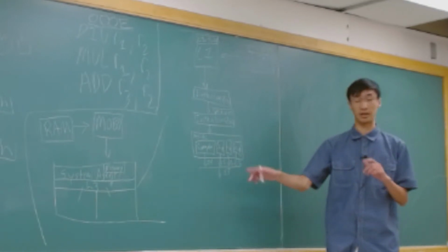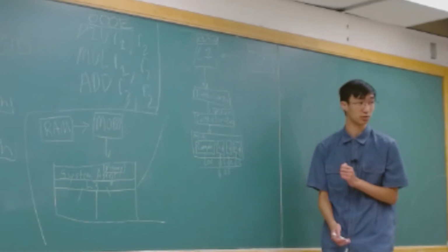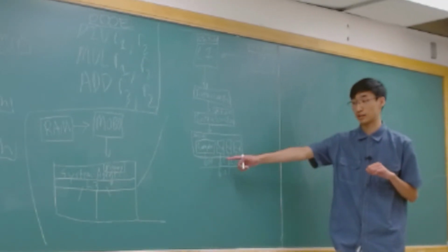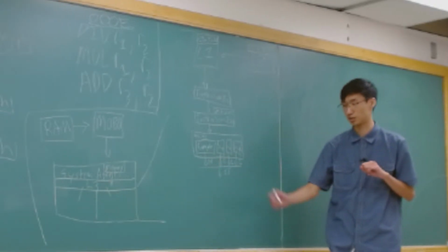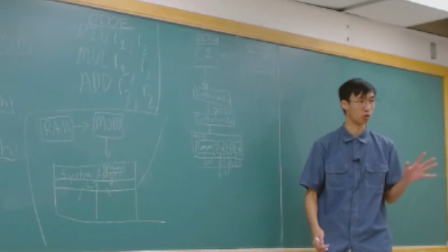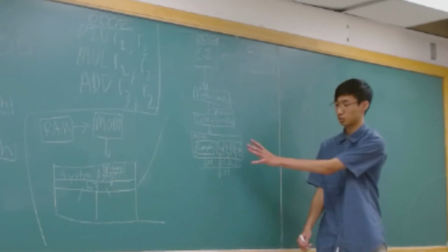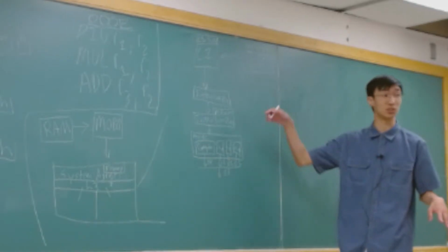This complex decoder will actually start turning off the simple decoders, or at least masking them out, whenever it starts running more micro operations. If you push anything into the complex decoder that winds up taking like 3 or 4 micro operations, the simple decoders start to turn off and you will get a lower throughput. So you'll get up to 4 micro ops, but you'll get fewer instructions through.